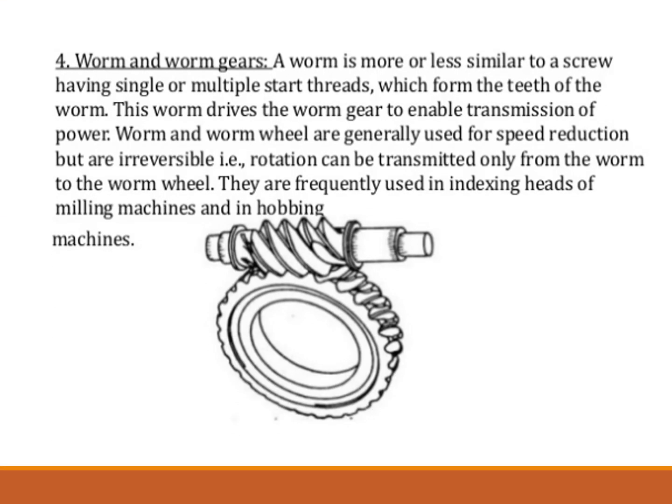Worm and worm gear. Another form of gear used to connect shafts whose center lines do not meet is the worm gear, which differs from all the preceding types of gear in that one element is a screw and the other is the worm gear with incurving teeth. Worm and worm gears are used when a large speed reduction ratio is wanted from one shaft to another.